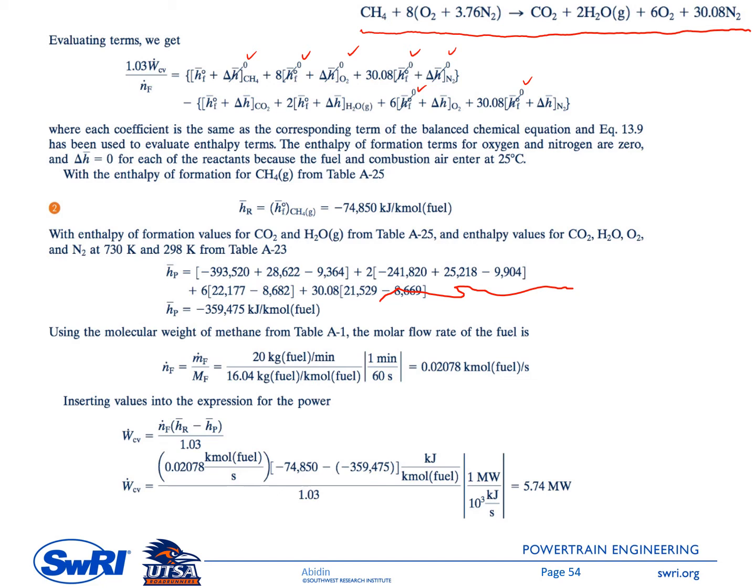Okay. So with the enthalpy of formation for CH4 from table A-25, we can get HR of this one, so minus 74,850 kilojoules per kilomole fuel.